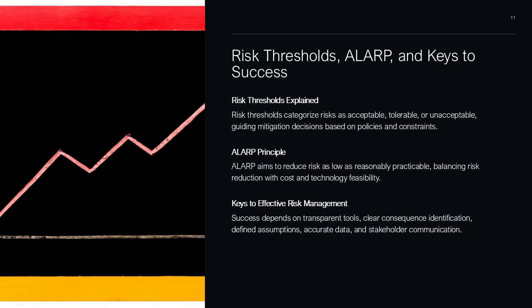In many cases, especially for higher-risk equipment, the goal is to reduce risk to a level that is as low as reasonably practicable, ALARP. This principle recognizes that while eliminating all risk is impossible, reasonable measures should be taken to reduce risk unless the cost is grossly disproportionate to the benefit gained.